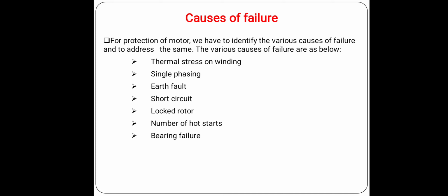Depending upon the thermal curve of a motor, we have to give certain time to bring down the temperature of the winding. If the temperature of the winding is high, then it may cause heating up or burning of the winding, and due to this the failure of the motor occurs.